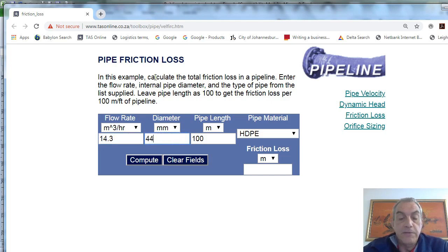You can check those specifications on whatever pipe you're using, but the point is that whatever dimension you're going to work on, it must be the internal diameter. All right, and now let's assume the length of pipe. For this pump station on an office complex, what you'd usually find is that they'll tuck the pump station with the storage tanks or the water supply. They'll tuck it there far at the back of the building, out of the way, out of sight, for two reasons.